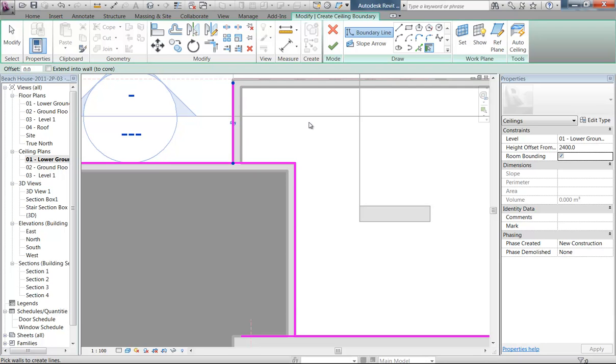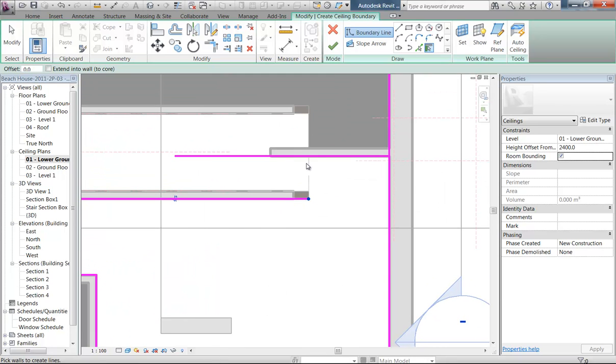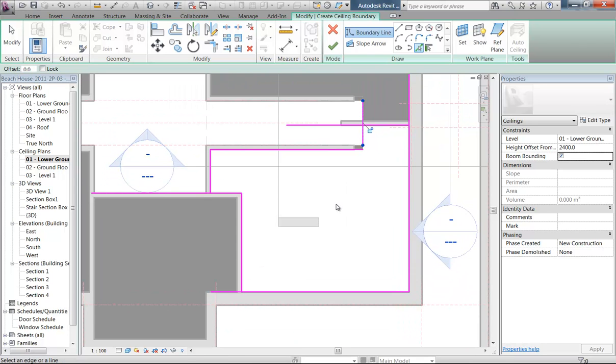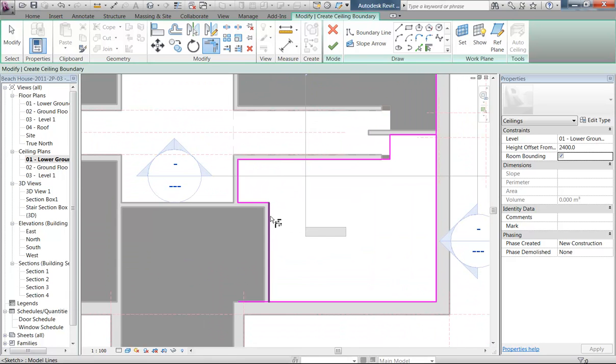So, if you put the ceilings on the inside of your walls, you're actually modelling them the way they'd be built. You can try putting them across the whole level, and there are different ways of building. You can have the walls stopping at your ceiling, but in residential, well, it depends actually.